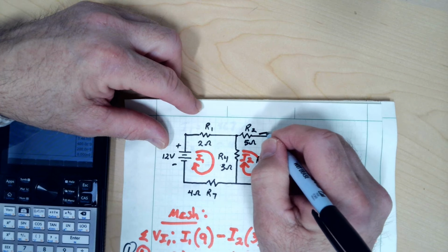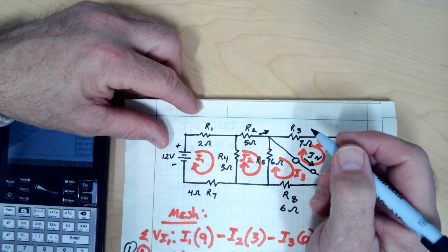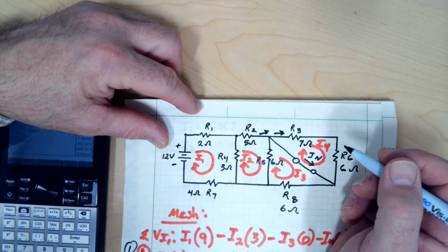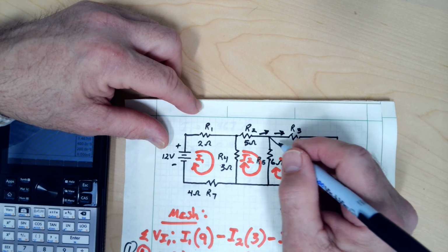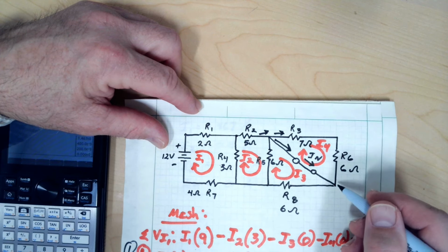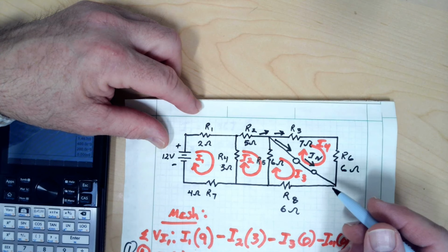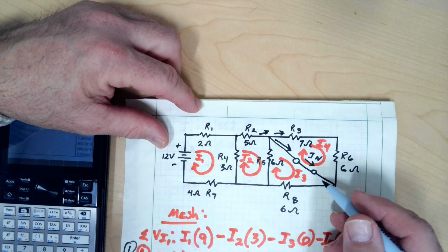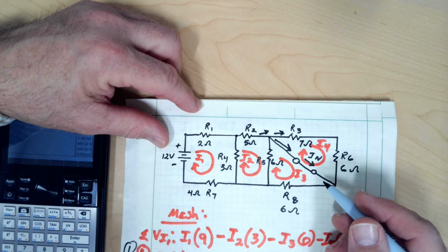You know, we have current coming into that node, and will any go that way? And the answer to that is no, not likely, because we have a short circuit here, so this part out here doesn't affect that Norton circuit value, because we are shorting through here. So yeah, I would expect that fourth term to indeed come out to 0 amps.